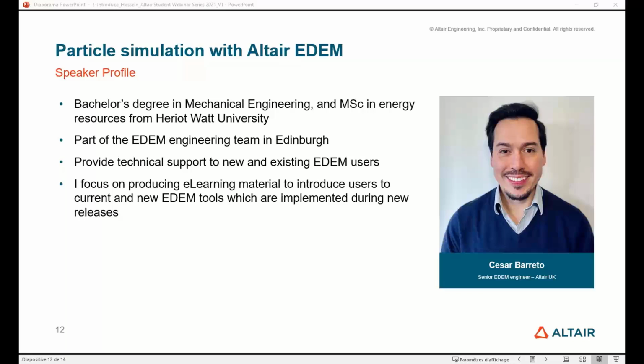So it all depends. During the presentation, we mainly see multisphere particles. However, we also have polyhedral particles, and it all depends on the type of application you want to address. For example, when you're using very specific shape particles that have high aspect ratio, like tablets or cubes, something very specific, then I would recommend using polyhedral, but it will be slower. However, for most applications, I think the well-validated multi-sphere approach will provide you with a fast and accurate calculation of contact forces, which are the physics.